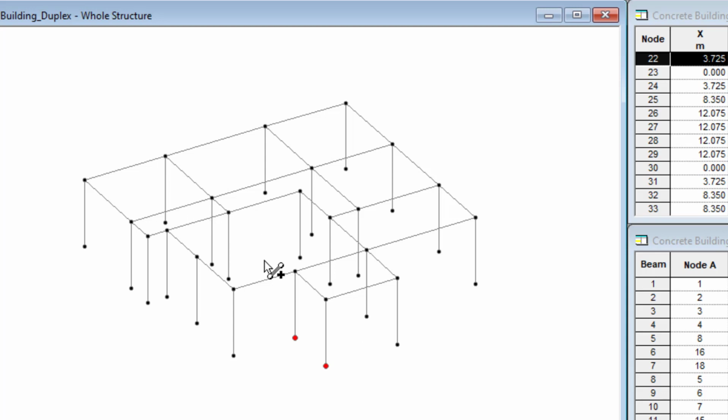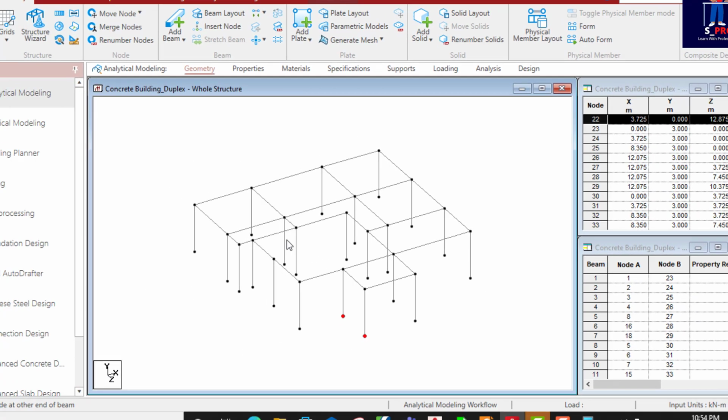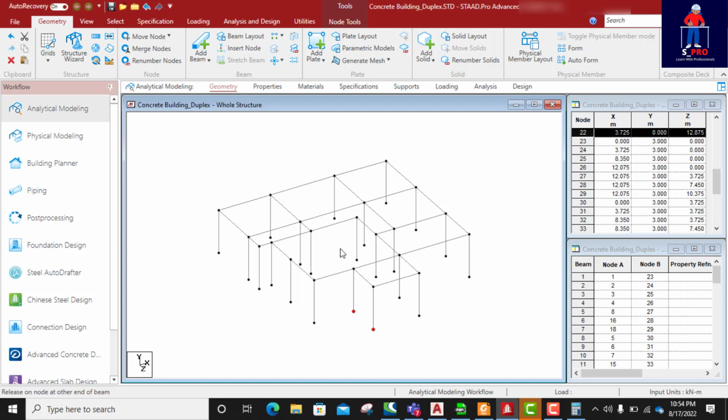Okay, another thing I would like to show you is this slab that will be here. This column is very large, is big. So if I don't introduce a beam in between, this slab will definitely demand a thickness more than 150. That means if I use 150, it will fail, maybe by deflection. So I will leave it like this for us to learn another thing. So if your slab fails, you know how to resolve it. I will leave it on purpose as well.